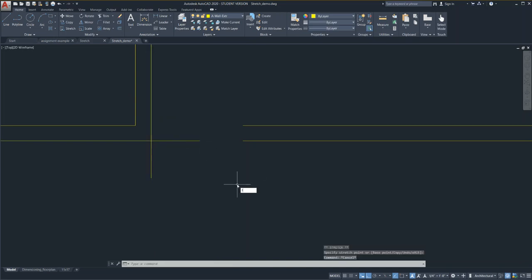Okay, F for fillet, enter. Now I want to show you something. AutoCAD remembers the radius that I had previously input. This says 6 inches. If I wanted it to be 0, I would type R, or click on radius, type 0, enter, and click once, click a second time, and it cleans that up. In this case, it was trim and extend in one command, right? But that's what we're going to use fillet for.